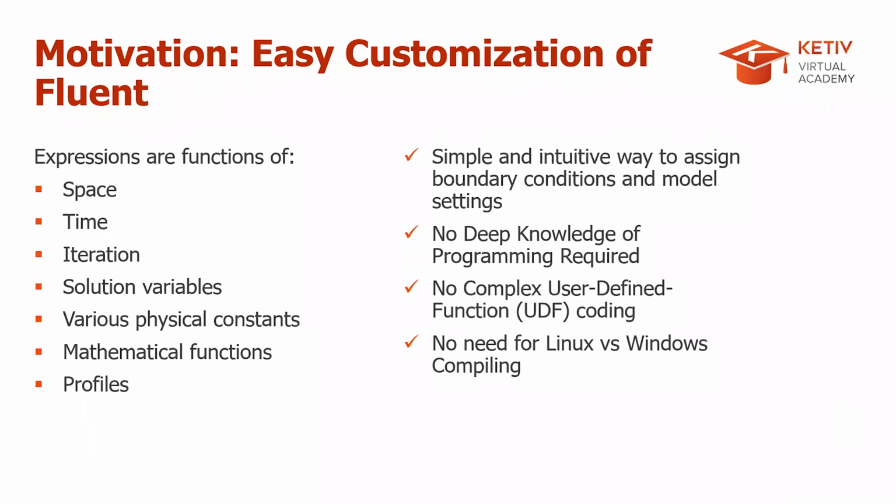And if you're not very familiar with the C programming language, then it becomes a whole lot of effort to understand how to write UDFs, how to interpret the different macros or different variables that go into writing simple functions for assigning complex boundary conditions and settings. So instead of doing all that, we can use expressions. It becomes much simpler to customize settings for your problem.